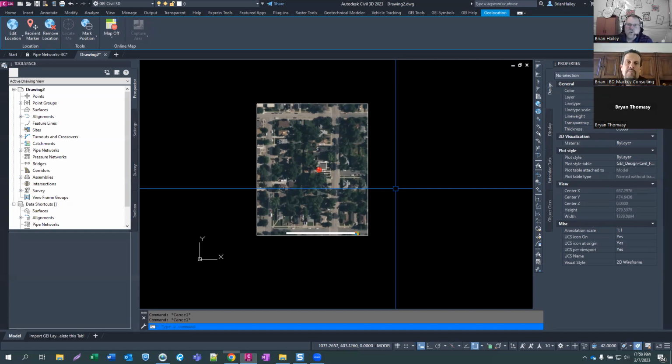There's four ways that I can think of to bring an image into CAD, at least off the top of my head. And that number might change as I go through this list. You can use the AutoCAD XREF. So if I go XREF, bring up my XREF manager, please. You can XREF it in just like you can with another drawing, a PDF, a DGN, et cetera. An image is one of the options.